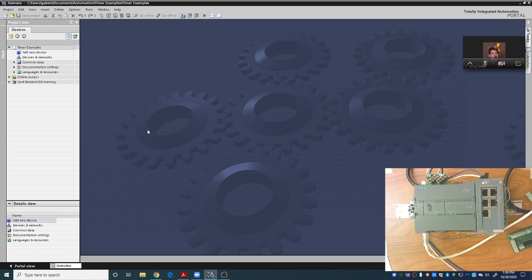We are going to be talking about how to reset your PLC back to stock. The first thing you do, which I already have, is open up Siemens TIA Portal V13, which is the version we have. Next, we need to actually find our PLC on the network. I do have my PLC plugged in via an Ethernet cable going back to my computer.